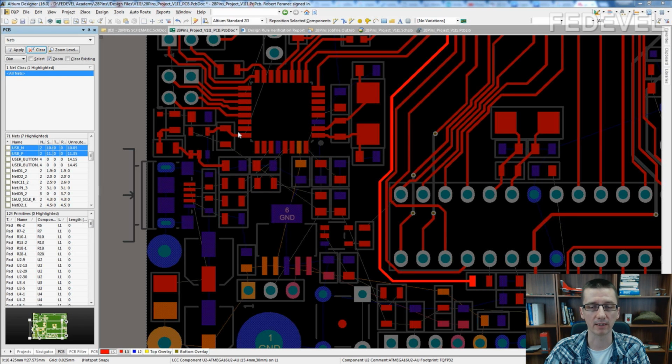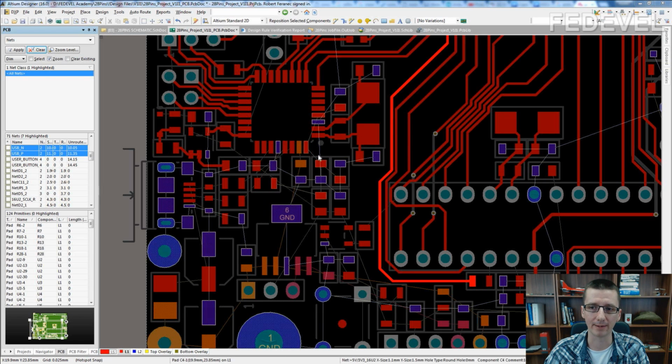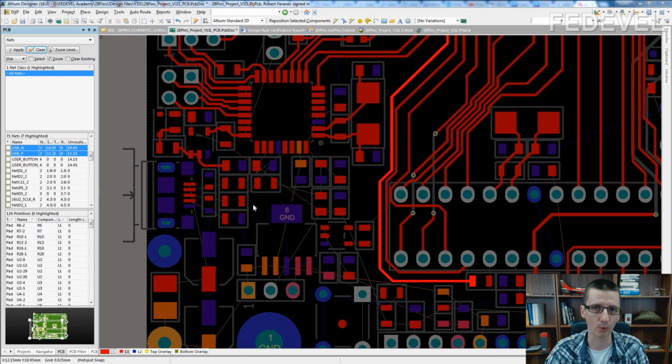What we will try to do, and if you are routing two-layer PCB and using signals like USB, what we should do, we should try to keep the USB connection as short as possible. Okay, these tracks here, we need to try them route as short possible, and we will route them together. We will use standard track width and standard gap. It's not the proper way how to route it, but on this two-layer PCB we do not really have many other options.